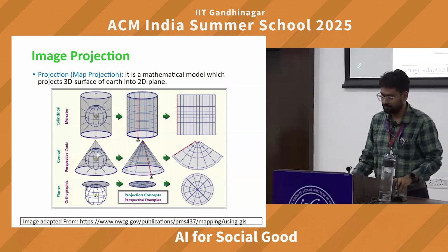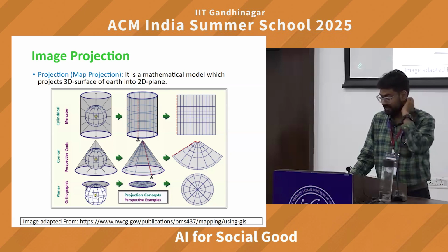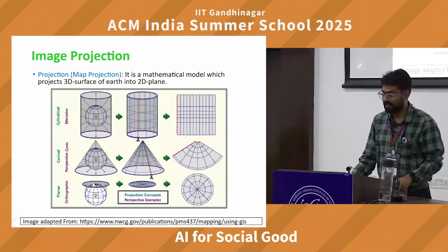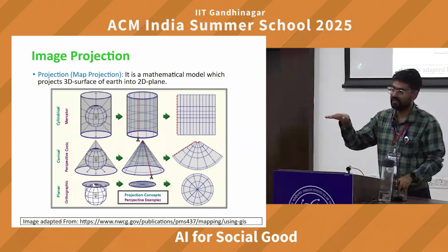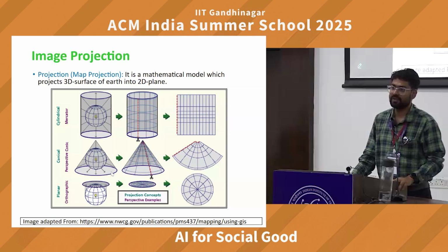Another example is planar projection, which is suitable for pole side map display. Here is a source of light, and you take the projection on the pole, where you assume that the projection surface is a simple plane, and you are taking the projection directly, since the poles are very close to the surface and the errors are minimal. Based on that, you identify at which location you are working and which projection you want to use for your applications.